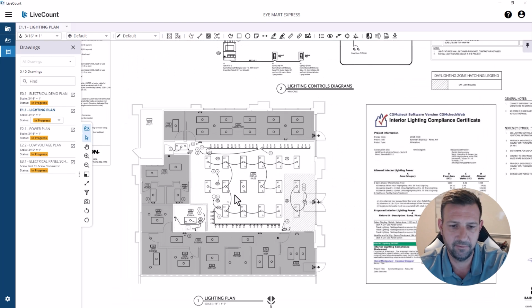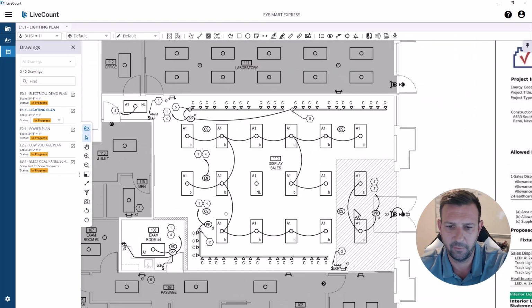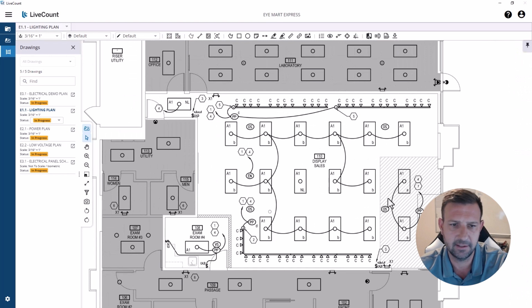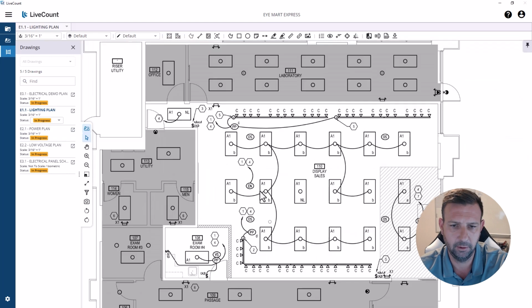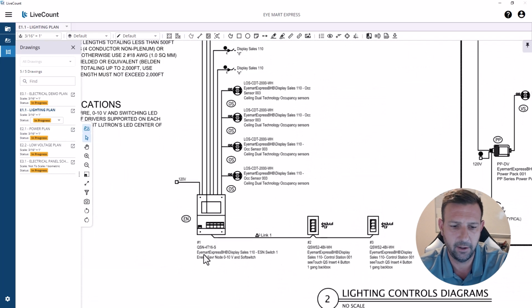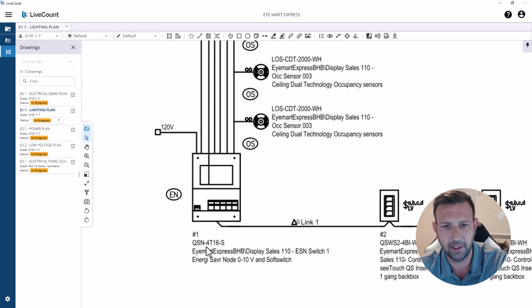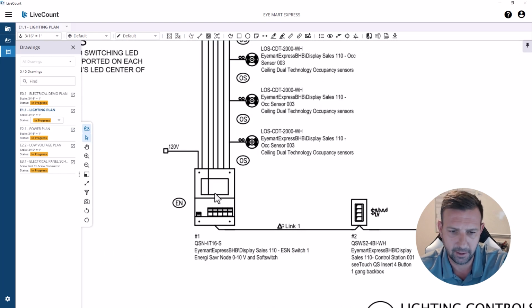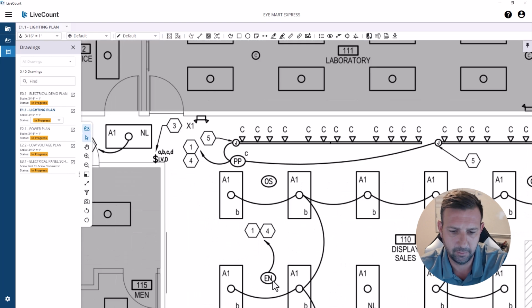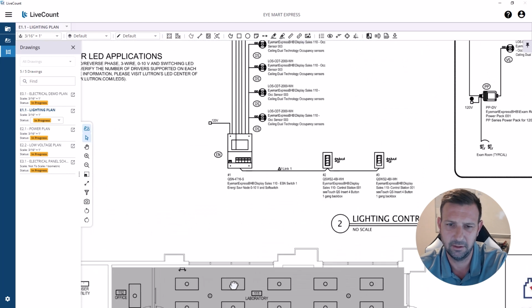We know there's some light fixtures going in. It looks like there's some 2x4 fixtures, some track lighting, a couple emergency fixtures, exit combos. Looks like there's some lighting controls that are interesting. I'll look these cut sheets up later, but looks like some kind of integrated lighting control panel. They're showing it to be installed maybe above the ceiling, which is a little strange.